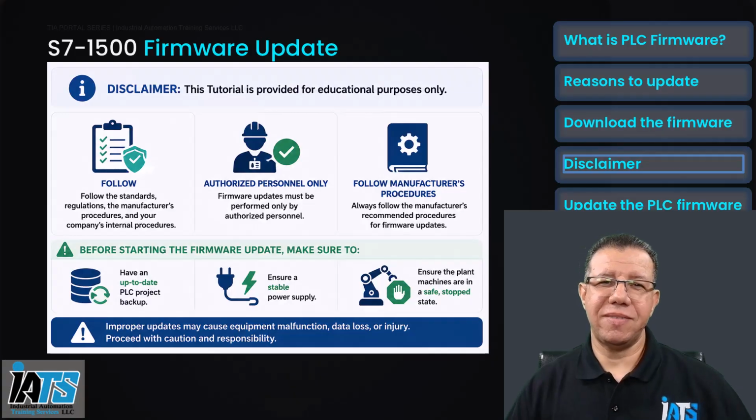As a disclaimer, this tutorial is provided for educational purposes only. Follow the standards, regulations, the manufacturer procedures, and your company's internal procedures. Firmware update must be performed only by authorized personnel. Before starting the firmware updates, make sure to have an up-to-date PLC project backup, a stable power supply, and that the plant machines are in a safe, stopped state.